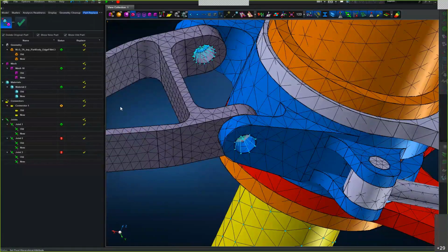So we have a whole bunch of mesh ties. Mesh ties don't represent any real physical connection, right? So we have joints, those represent real joints. We have fasteners and connectors, those represent real fasteners and connectors. We will add adhesive joints where we will be modeling the adhesive.